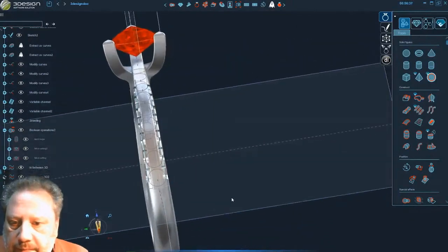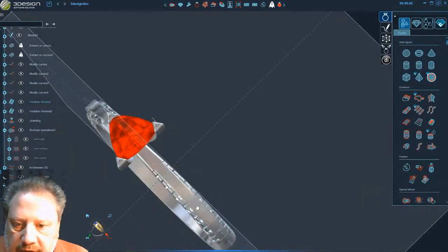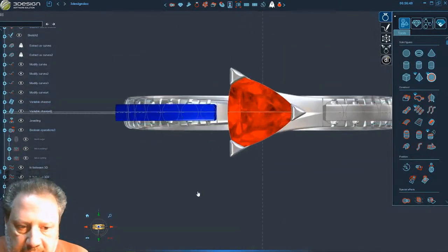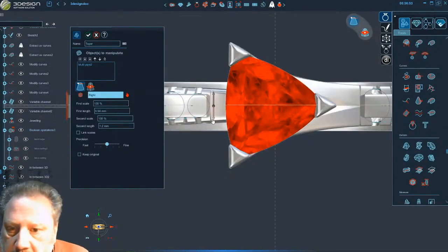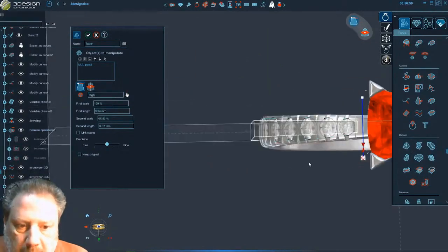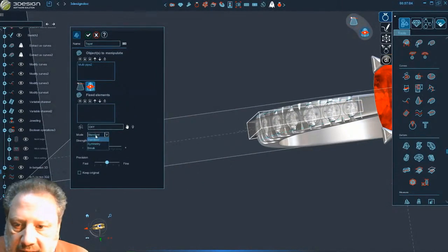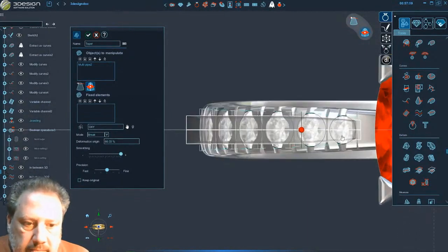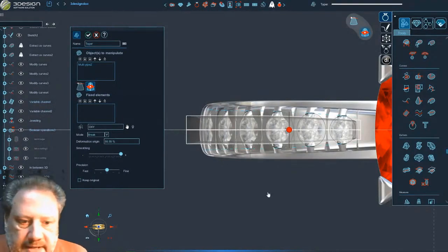Okay, now as you can see, the shape will be a little bit more narrow here. So I'm going to adjust it by simply doing a taper, and drag it a little thinner. Okay, then I will use the advanced tab because it's not everywhere, and I will go for a break. Not me, but my multi-pipe, of course. Okay, looks good. Let's validate.